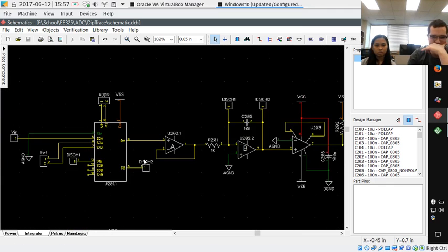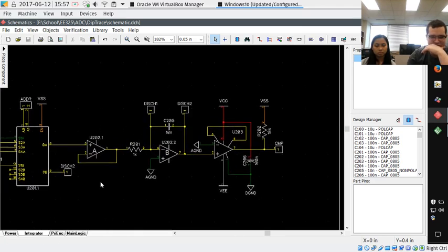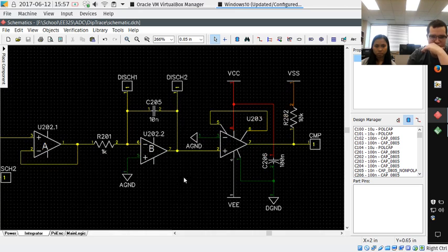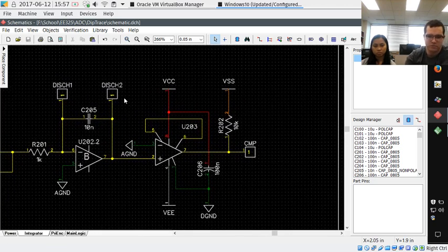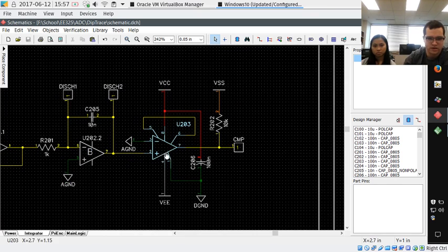The switch IC has 2 switches in it that operate simultaneously. So we are also able to make sure this capacitor is discharged by putting at the most 100 ohms across these terminals. It'll probably be less than that, but basically it will help to speed up resets. Here's the comparator. It's an open collector design.